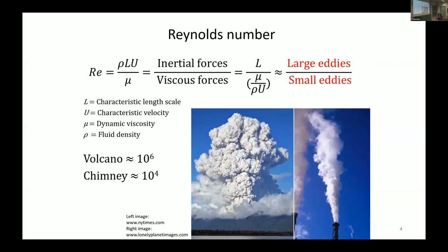If you want to squeeze this into a lab at high Reynolds numbers, the large scales are going to be limited by whatever facility you have, by the lab, by how much money you have. So if you want high Reynolds numbers, you will end up with small length scales. That's the unfortunate fact with high Reynolds number investigations in a lab.